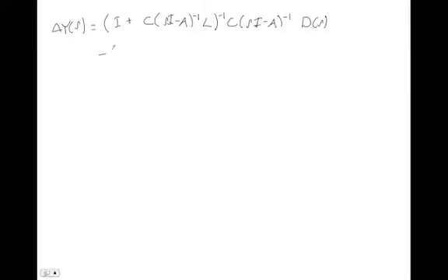And then we have this other term, identity plus C (sI minus A) inverse L, inverted, times C (sI minus A) inverse L. This is the only difference, times our noise. So we have these two big transfer matrices that relate noise and disturbance to our output y.